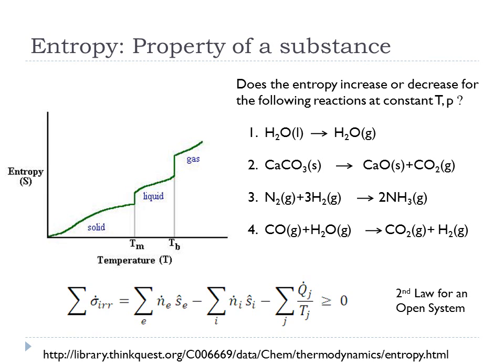From the second law, what we said was, and we look at the bottom, the irreversible entropy generation within a control volume has to be greater than or equal to 0. And what that means is when you rearrange that equation, the other way of putting that is that the sum of the three terms, these two n dot terms for all the moles that are entering or leaving, as well as the entropy associated with heat, has to be greater than or equal to 0. And that's what the second law of thermodynamics is stating.